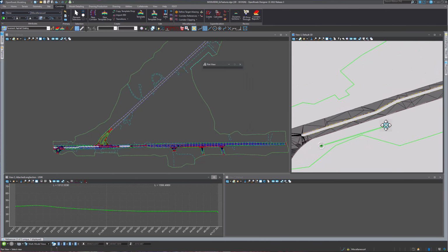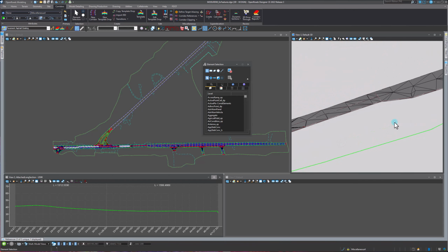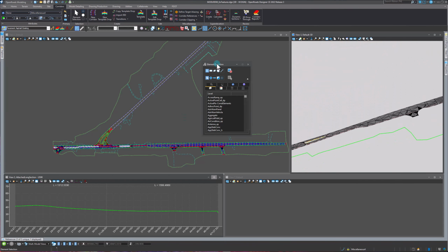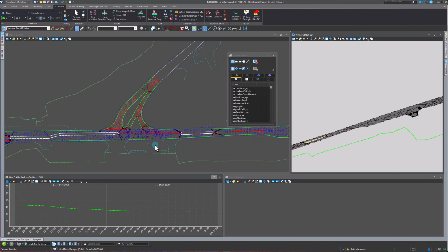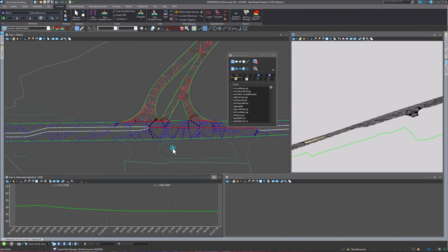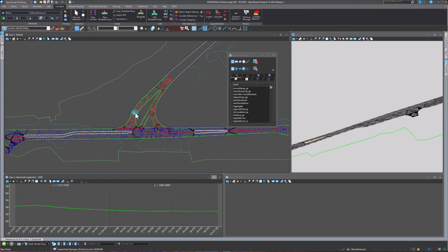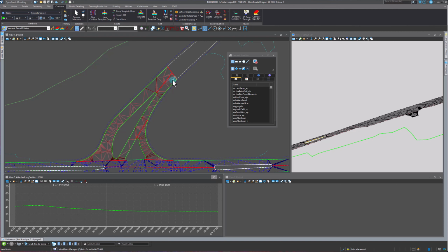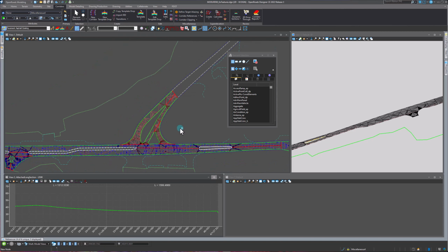Okay. So, we can see we've got depth here. And I know I mentioned parametric constraints in those labels before. And I realized that I don't think there's any way to apply a parametric constraint to a surface template. Those really only apply to templates that are in a linear template or a corridor. So we set this to 1 foot, I believe, in our surface template. But let's say we know this pavement is 14 inches or something like that, or 16. Let's say it's a little thicker.